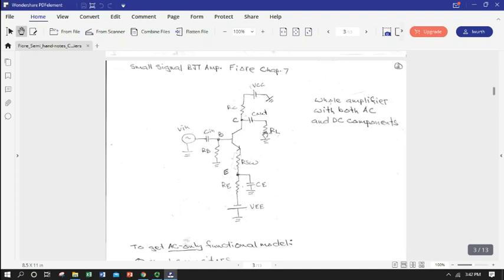And because from the standpoint of the load, looking at the way current would flow, from the standpoint of AC, really this collector resistor and the load resistor are truly in parallel. So if we're looking at gain, we're actually going to put the load resistor and the collector resistor in parallel when we define voltage drop for the purposes of gain calculations.